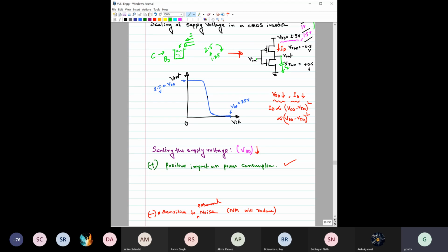So your friend was earlier saying that the resistance is remaining the same. So is it then valid? Is the resistance remaining the same? No, sir. The resistance is basically R naught of the NMOS in parallel with R naught of the PMOS, so R naught by 2. R naught is proportional to 1 by lambda ID. So obviously R naught is inversely proportional to ID. So if ID decreases, R naught increases, and the RC time constant increases.